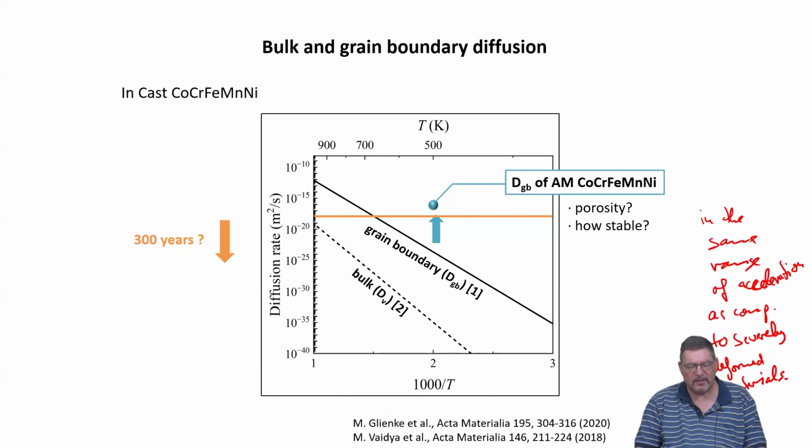So it means, this is why the title of this part of the lecture came about. In terms of their diffusion coefficients, these grain boundaries after additive manufacturing show similar diffusion behavior as some fraction, about a third of all the random high angle grain boundaries in severely deformed material. So they show this unusual non-equilibrium grain boundary behavior. This favors precipitate formation. Additionally, they also have a different segregation behavior, showing more segregation at their boundaries.